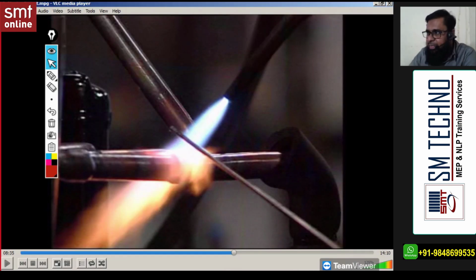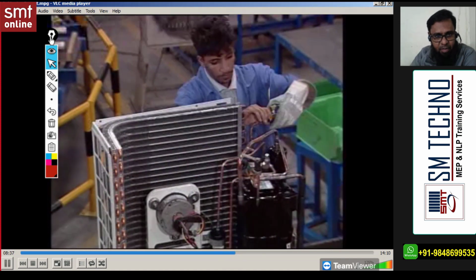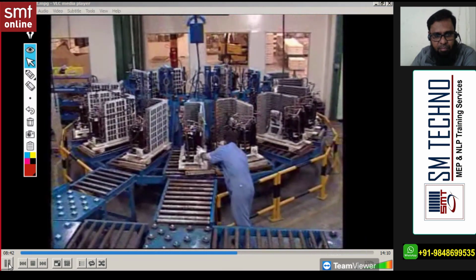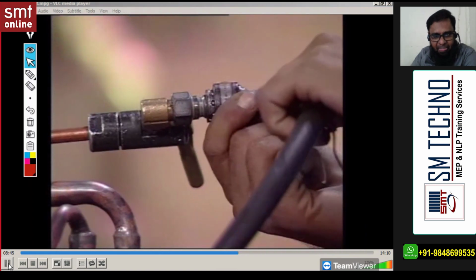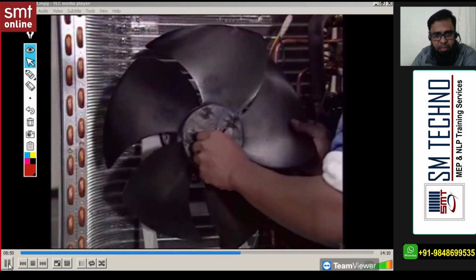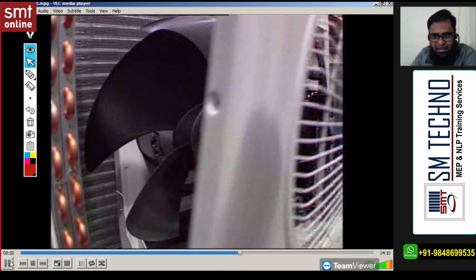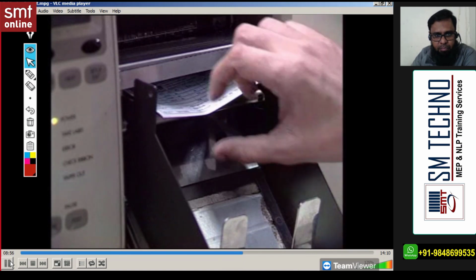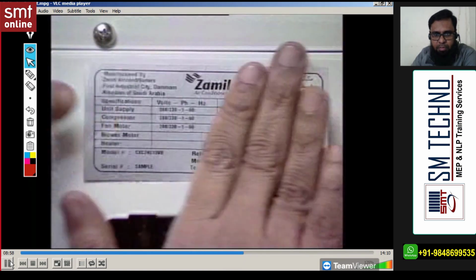You know this brazing. Brazing and dehydration means vacuumizing, extracting the air from the heat exchangers, then refrigerant charging in the compressor in gas state. After brazing, units are pressurized for air leaks and dehydrated. Final assembly, including electrical control box and wiring, permits one last functional test prior to packaging and stocking in the finished goods warehouse.